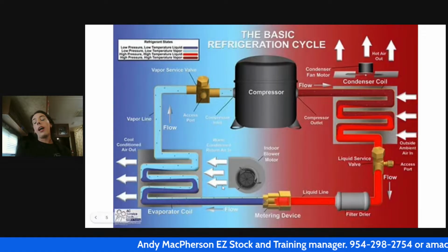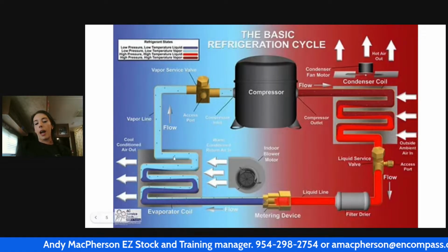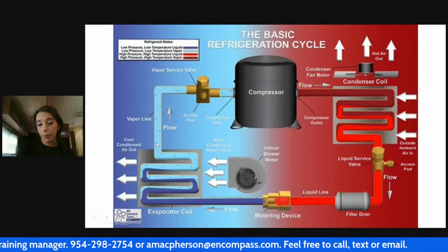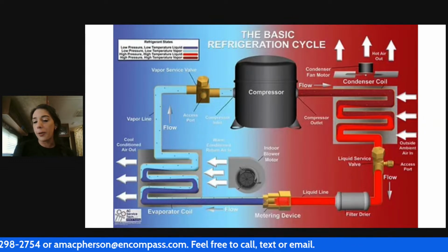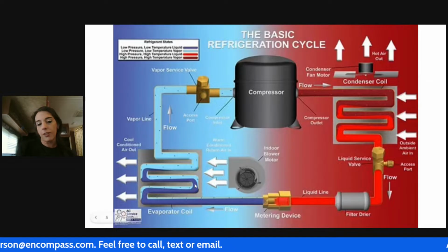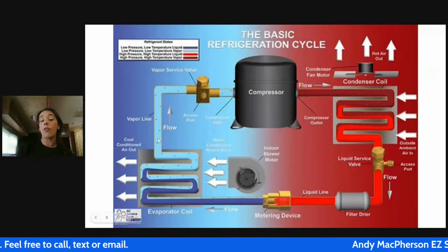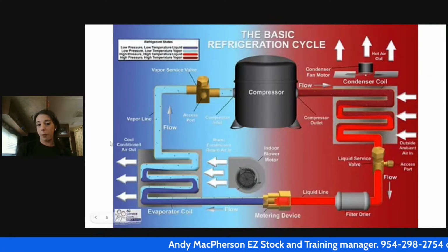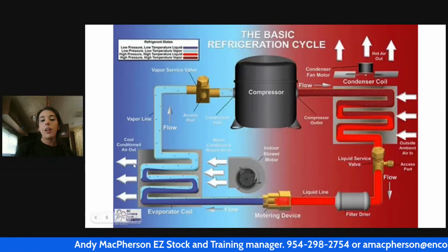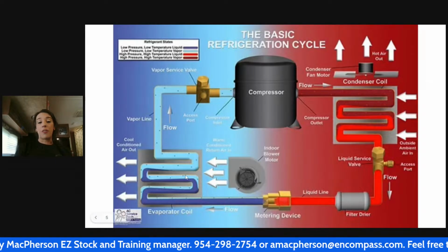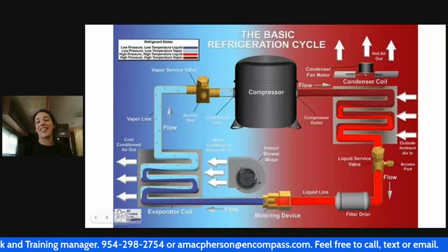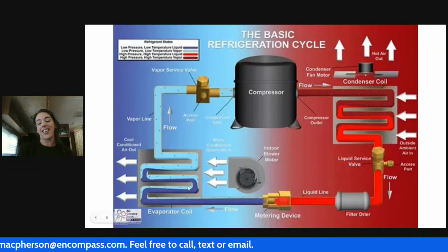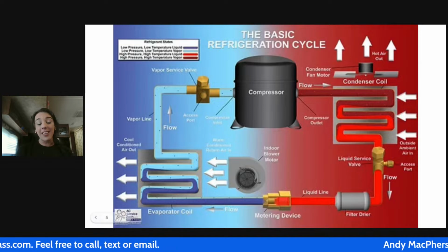So if this evaporator is 40 degrees, okay, I can tell that this phase change is happening how it should be because I know that my design vapor saturation, my VSAT, is 40 degrees. So if I'm close to 40 degrees, I know this phase change is happening where it should be in the coil. And I know for a fact that vapor refrigerant is going back to my compressor because I wouldn't have a 40-degree evaporator otherwise. Now, that's in a perfect world. And anybody that's an HVAC tech watching this, you're gonna be screaming at the screen right now, being like, yeah, right. So yeah, it does happen in the field, but more often it's not correct.